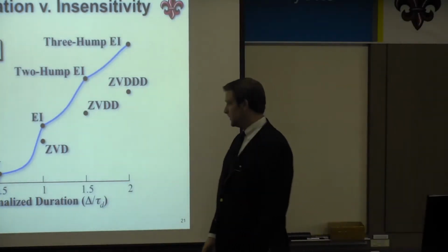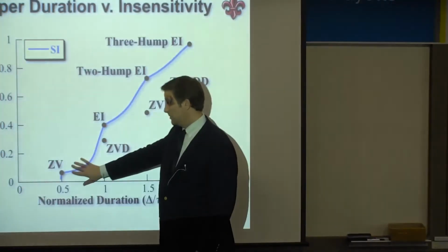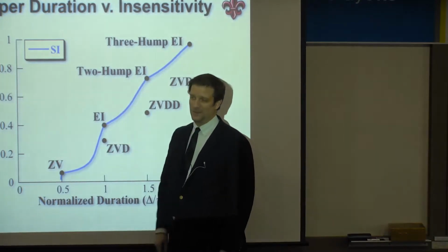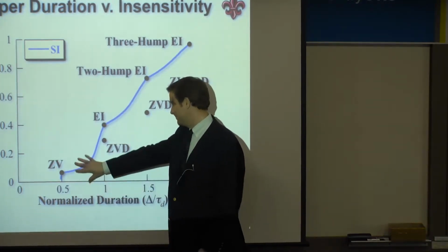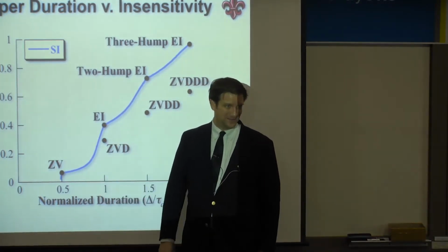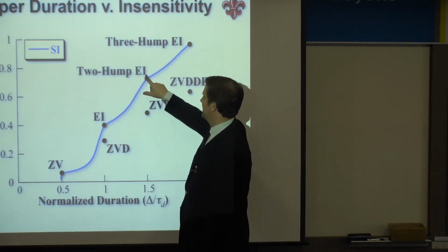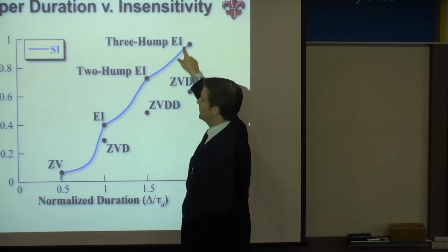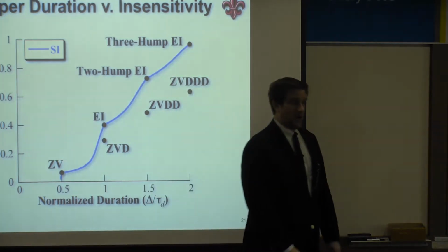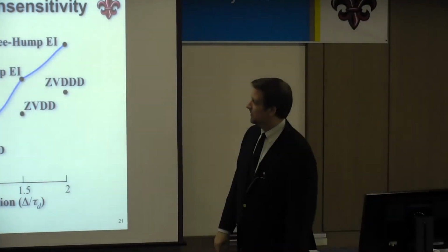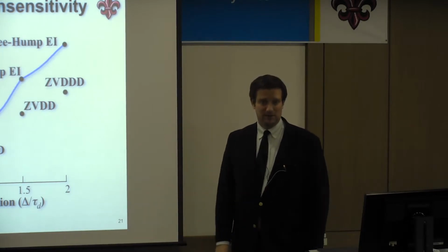So in this lower part of the curve, what you really want to do is a ZV or an EI shaper. That's the moral of that story, I guess. And even up here, there's not as dramatic a trade-off, but these EI shapers, these ones we know in closed form, are kind of the time optimal solutions for that amount of insensitivity.